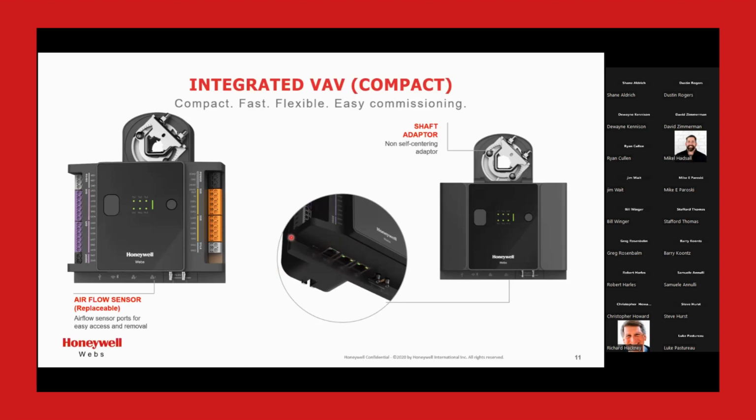And depending on which 7 you're looking at, it may be BACnet over IP with an RJ45 jack. The new optimizer unitary controller offers the Ethernet jack as well as something called T1L. We'll talk about that in a minute. And we're working on a Wi-Fi only version. So you'll have actually eventually 4 flavors. You'll have BACnet over twisted pair, BACnet over Ethernet, BACnet over T1L, and BACnet over Wi-Fi. And this is all going to be part of the Spyder 7 optimizer.